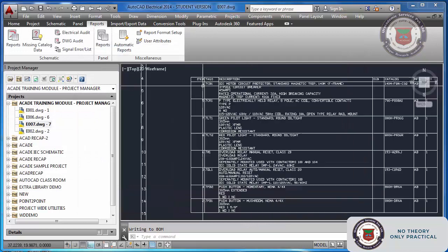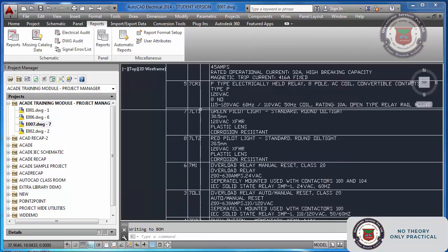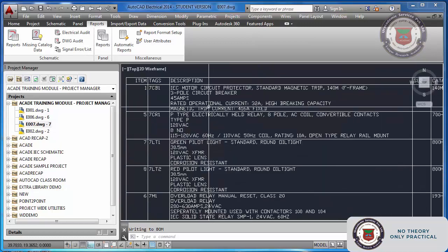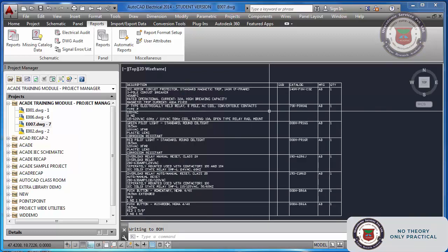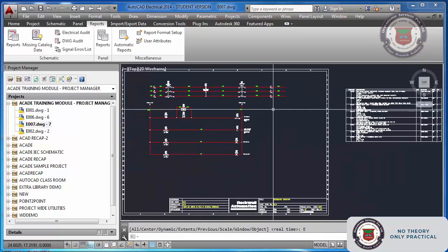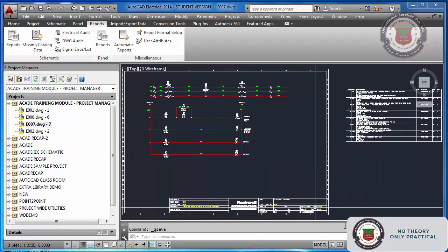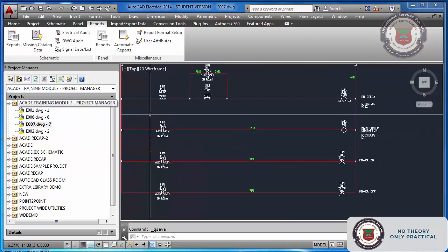Close. Now you see item number 1, 5, 6, 7, 8, 2, 3. We can sort these item number wise. Okay. Description, that line-up has gone now. That entity has gone. We have not deleted that. In fact, it has been updated with a new one. In this way you can create and insert bill of material.